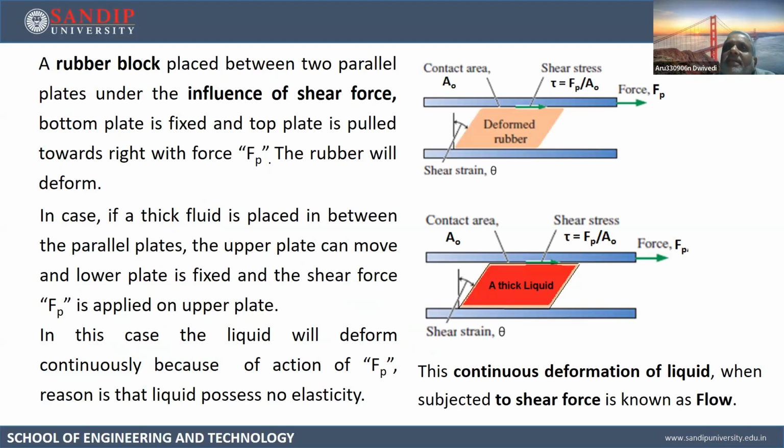So you are placing the eraser in between these two plates and you are gluing it, right? You join it with some Fevicol or the like. So that is a rubber. You are just gluing it in between the two plates. Now the lower plate, you are just screwing it on the table so that the lower plate cannot be moved.